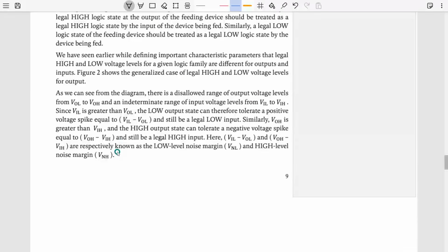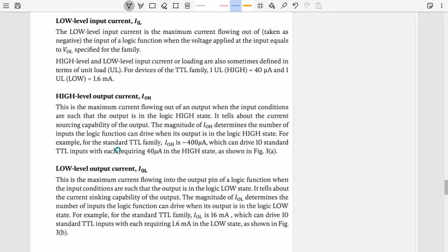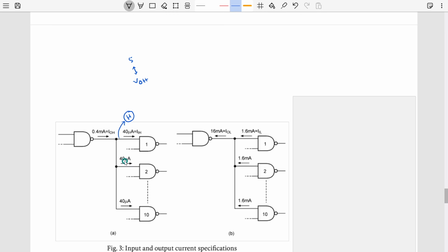But you have to understand, in this particular circuit we are seeing here, whether you give 5 volt or VOH or any value within that region, based on that voltage, current will vary through this path. Current may increase or decrease, right? So we cannot just say that if we provide logic high, then this is the maximum current.